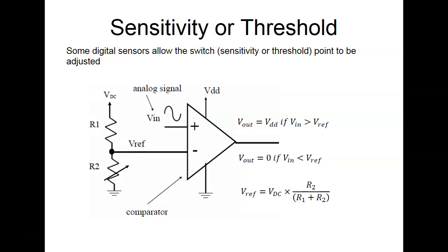There's no such thing as solid black, so even black reflects some light off of it. So what we can do with the sensors is adjust it so it doesn't see black. We can adjust them so sometimes they see black and sometimes they don't. And it uses that to determine how it puts the cylinder together. So these have a span adjust on it, right? Where you can set where it trips.